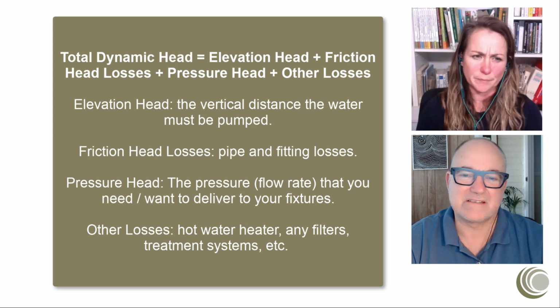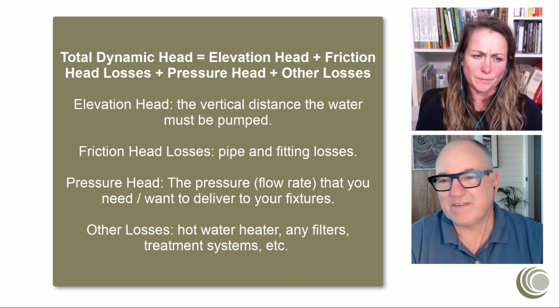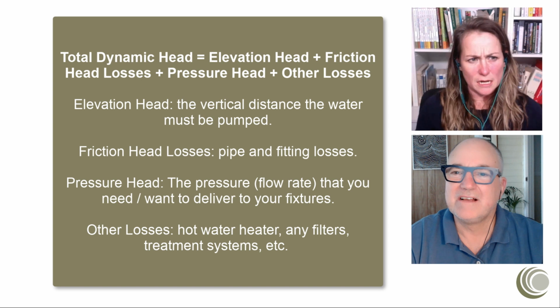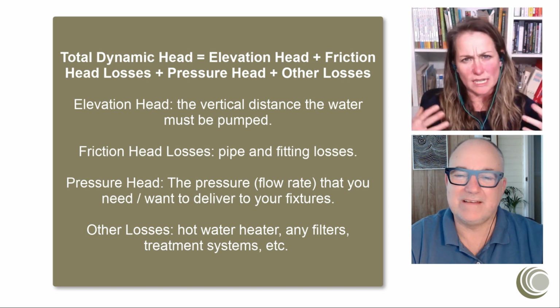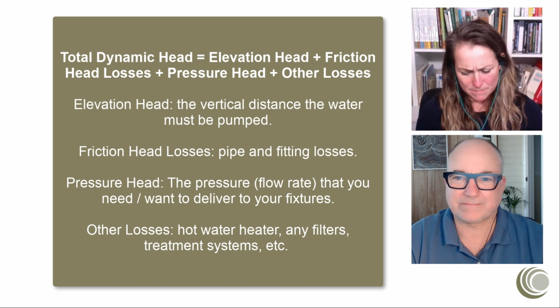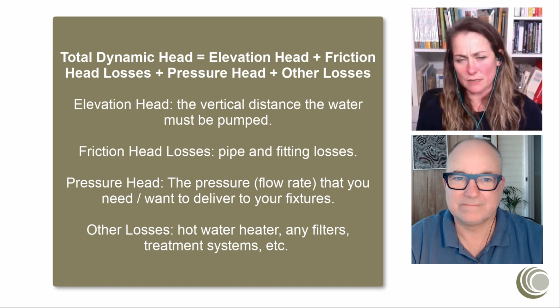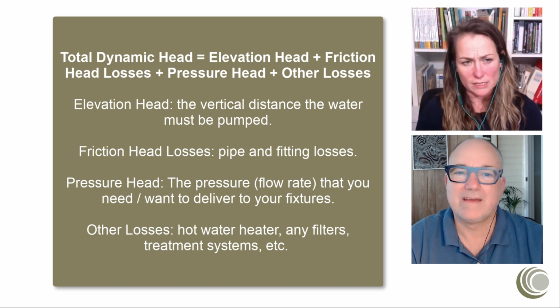Right? Friction losses. Be aware of the elevation head, which you've put up on the slide there, Michelle, because that's part of the total dynamic head, the amount of head pressure that your pump needs to supply, right? All the losses.